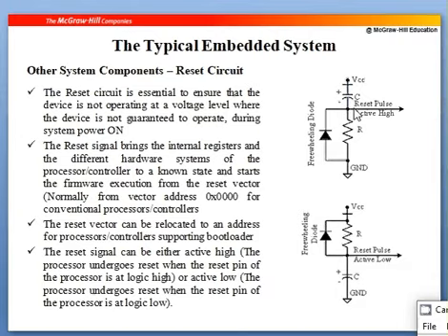Now all of a sudden this will give you a high voltage. For a small duration you get a high voltage due to the capacitor's voltage. The capacitor is going to discharge the voltage it has for a small time, and that small time is defined by the values of C and R. If you want that time to be sufficiently large, then set the values of capacitor and resistor as required. So you get kind of a spike.